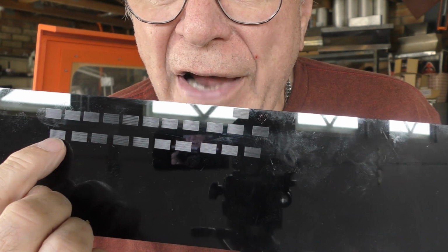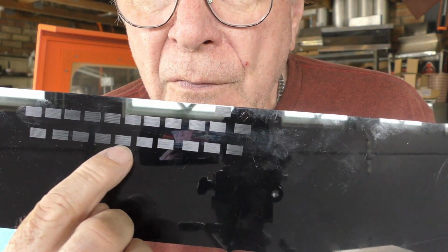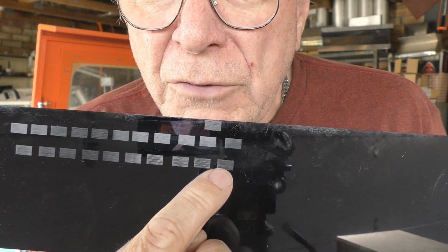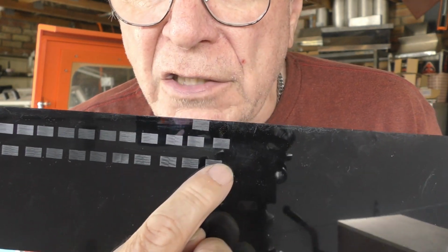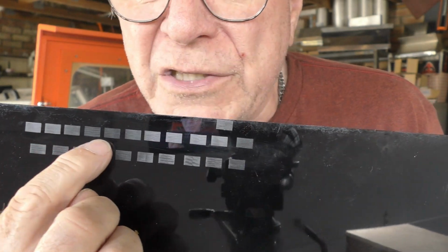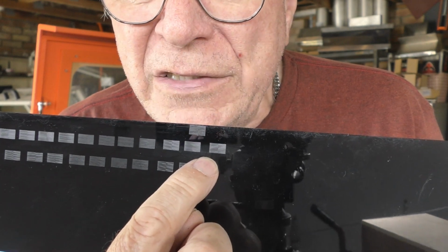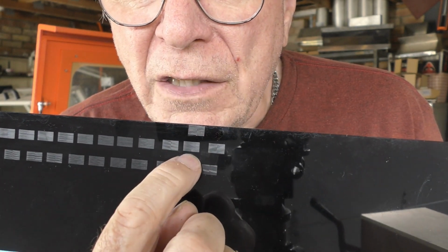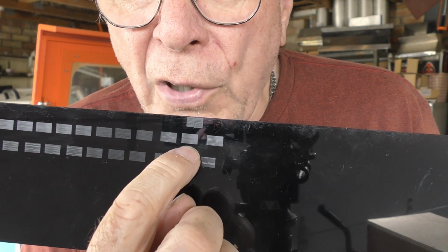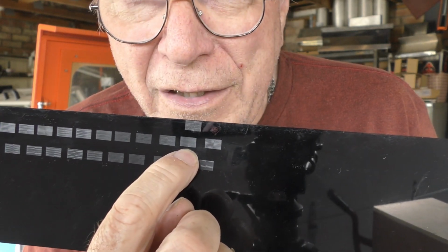10.002. In other words, I added 1 hertz to each one of these and checked what was happening. We're not talking about 10 or 100 hertz, we're talking about increments of just literally 1 cycle per second in 10 kilohertz. And the one that came out best was this one here, which is 9.999.